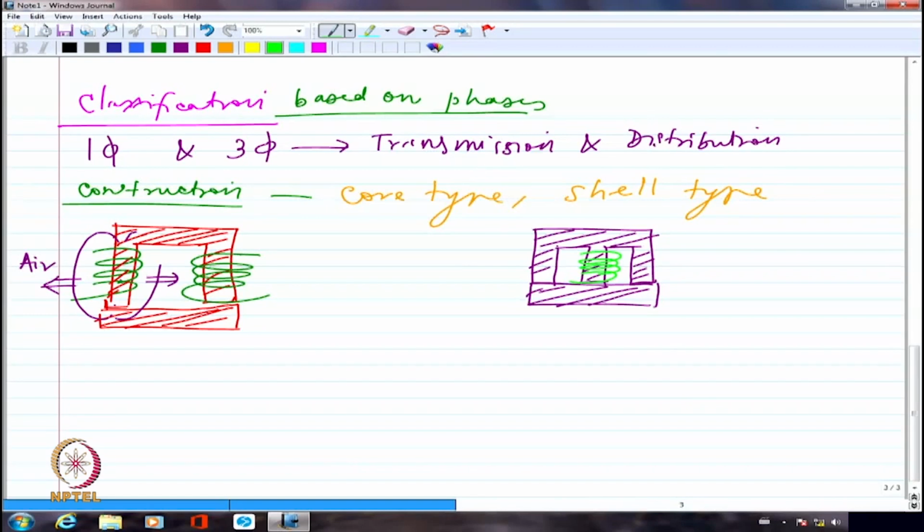So the reluctance in this case will be really, really low, because of which the entire magnetic field lines will try to confine themselves only within the core, either like this or like this. Hardly anything will escape into air. Whereas in the other case, because I have a larger amount of air surrounding the winding, I may have more lines leaking into the air.